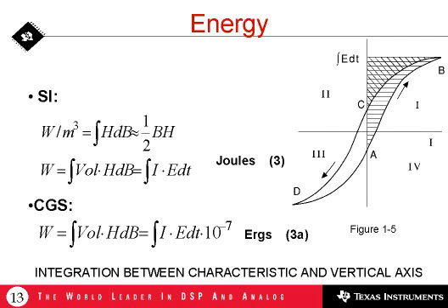Now, we reverse direction. We go from B back towards C. Now, the volts-seconds throughout that entire excursion are positive. But the voltage is negative. It has to be negative if we're moving in the negative direction along that axis. And so we're still in the first quadrant. The current is positive, but the voltage is negative.